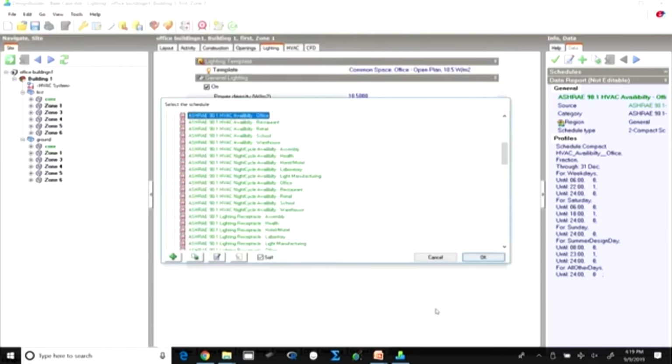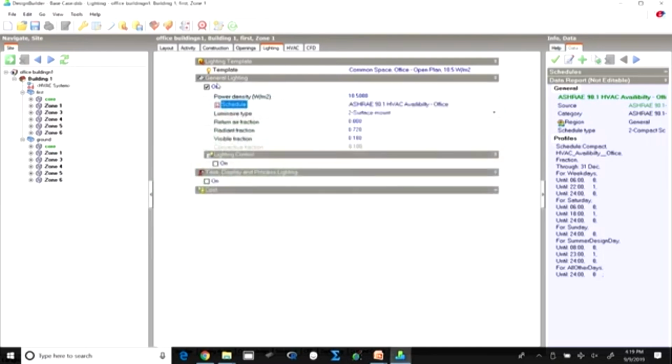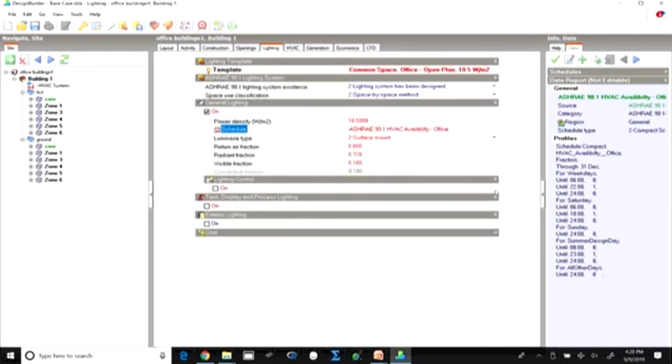However, when we go on to design and simulate the proposed case, the moment we turn the lighting controls on, which will imply that the lights will be on only when sufficient daylight is not being made available, we can immediately see the difference that will be brought in the electricity consumption because of only adding the lighting controls. So, this is what we will provide as an input right in the beginning for the base case.